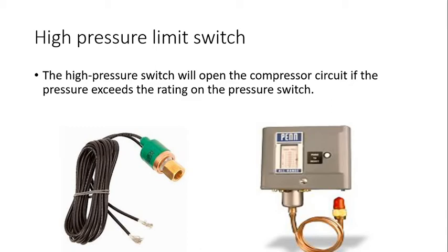Unfortunately, some people go months and don't know what's happening because it waits. The high pressure builds up when the house has been cooling for a while, it shuts down, cools off, and then comes back on. So there could be a high pressure problem, even with a kickoff switch, that is causing a possible problem and will cause compressor failure even though no one would know it. The one on the right side is for a refrigeration system, like a cooler or an ice maker or something like that.